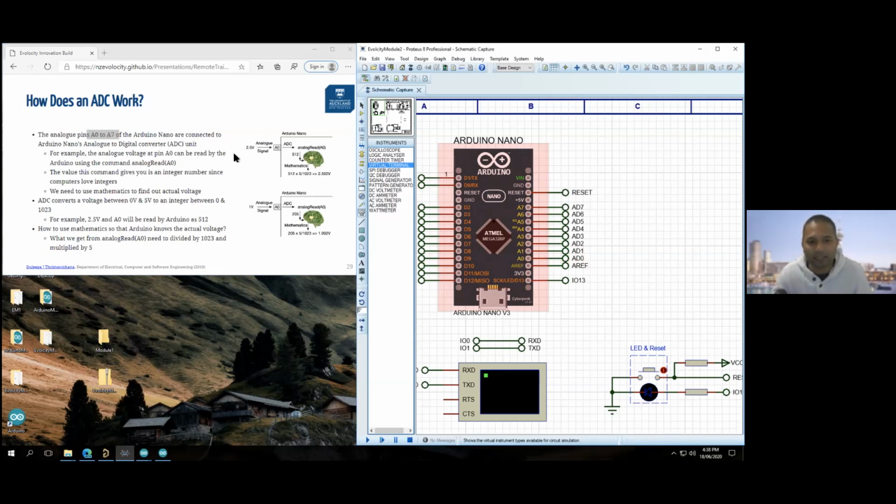and assume that the analog signal has a value of 2.5 volts. So if you put in 2.5 volts, what the ADC does is, in the Arduino, it has 10 different ones and zeros, which is a number that can count up to 1023. Then it'll say, I know that 0 represents 0 count, and 5 volts represents 1023 count.